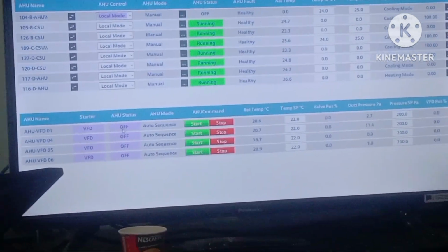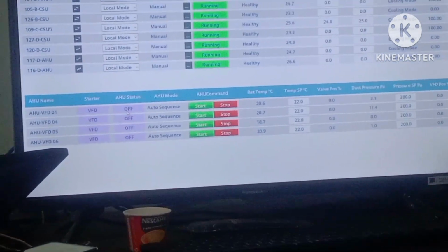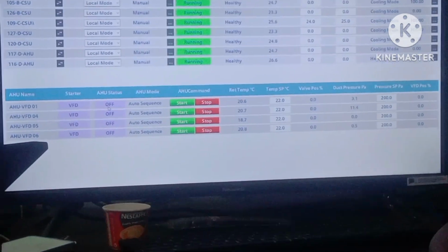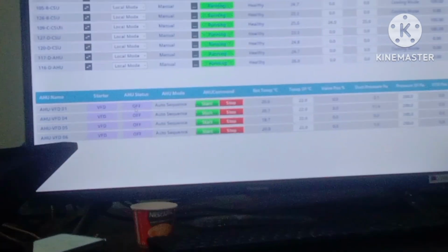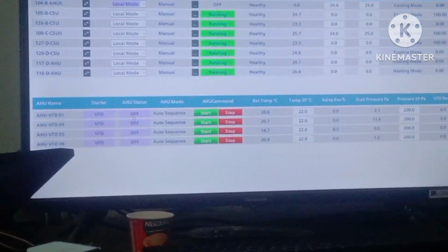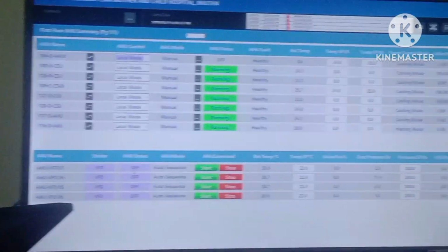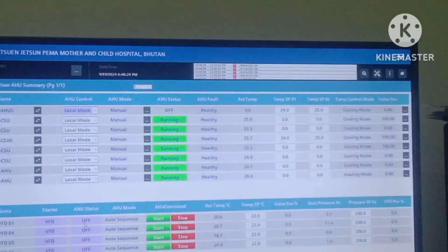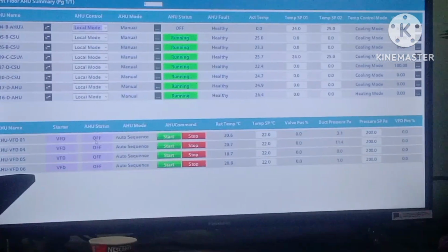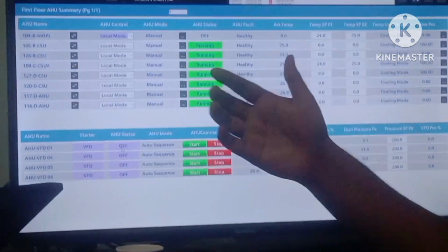The AHU is running on the maximum speed. Like there is a VFD and bypass. So rest everywhere, everything is running in the bypass at the full speed. Only where the VAV is present, there we have the VFD. Clear? Other AHUs run at the normal speed. If you reduce the temperature, the fan will be rotating at the same speed. No switching down.